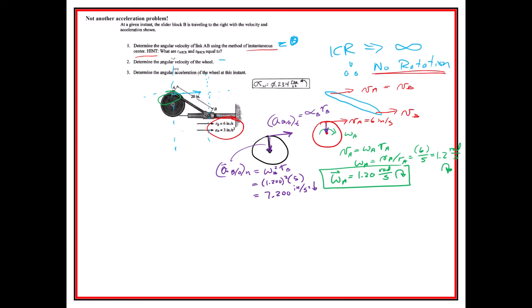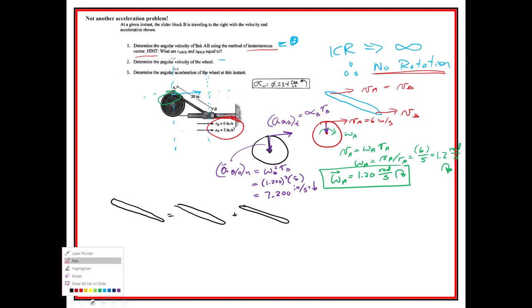Then we take the acceleration diagrams, the 3-diagram method here. Accelerations that we know. We know the acceleration of B. We don't know this acceleration. I'm assuming it's going to the right. I got to be careful with that. If I get a negative, then I know I did something wrong. Actually, a lot of times I will just leave that alone. I won't commit to it.